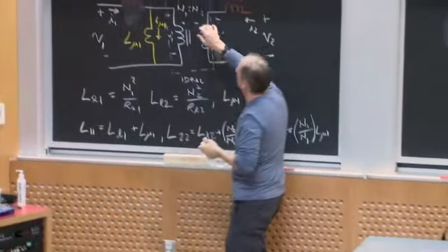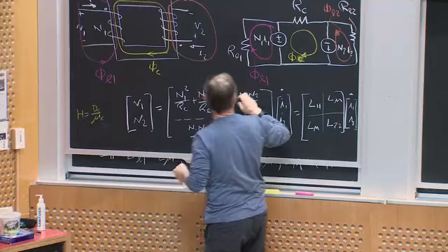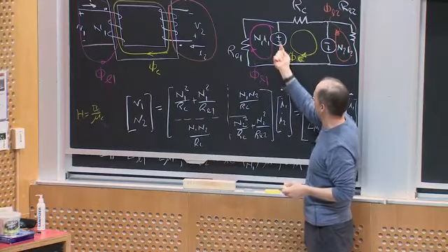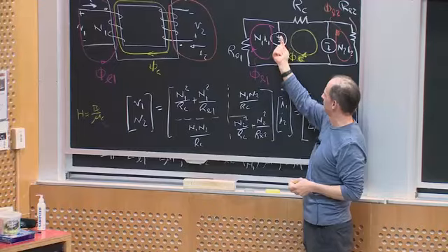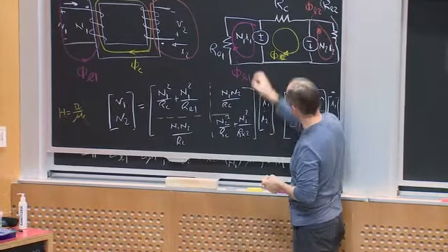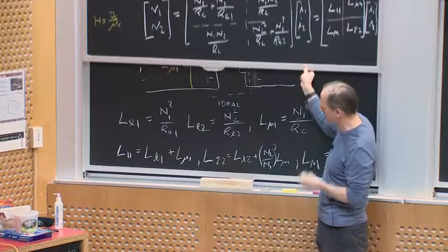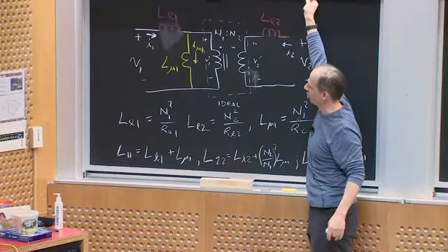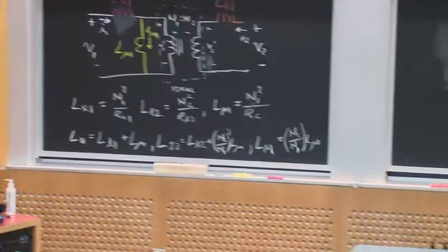Remember, the flux that's of interest for the flux linkage to relate to voltage on the electrical side is related to the flux coming out of the positive terminal of the MMF source. So you have to pay attention to your signs, especially when you have multiple windings, and that comes back to representing Lenz's law. Let me stop there and ask if there are any questions.